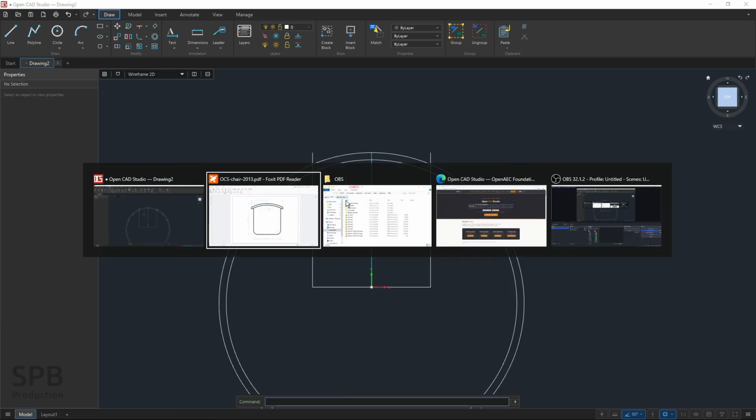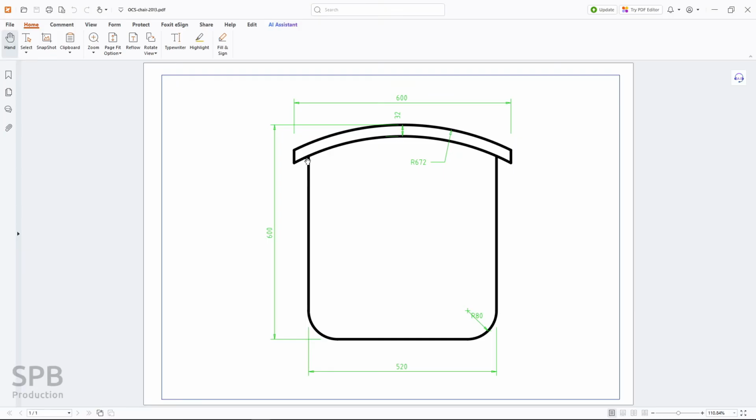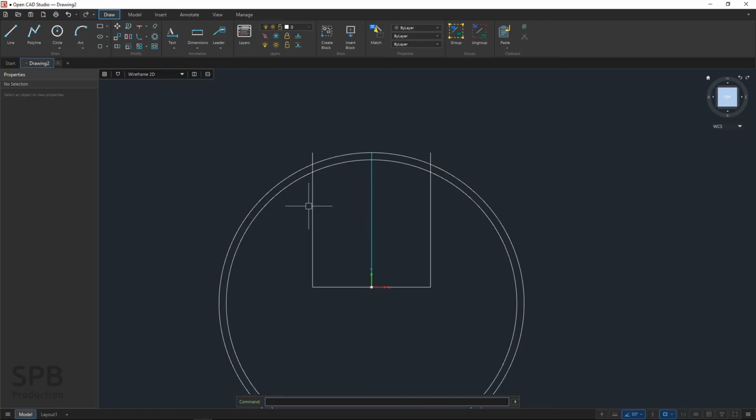So now what we can do is, we have these lines created up to here, so I can cut them away because I have the basis of my backrest there. So to make the drawing more clear now, I want to cut this part of this line. So I will fire up the trim tool, which is this one. And now it's asking me to click segments to remove. So I will click this segment and it's cut away.